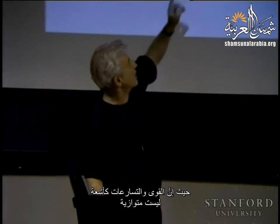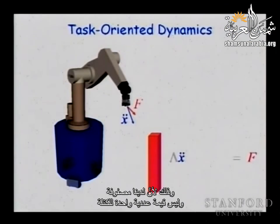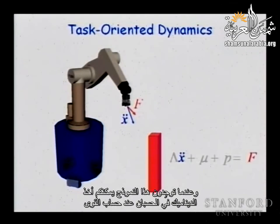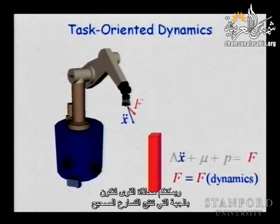That is, forces and acceleration are not aligned because of the fact that you have a matrix. And because of that, you need to establish the relationship between the two. And once you have this model, you can account for the dynamics in your forces, and then you can align the forces to move, to be in the direction that produces the right acceleration.